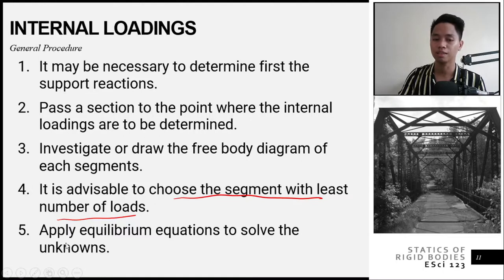Then after that, you apply your equilibrium equations: summation of forces x, summation of forces y, and summation of moments. Okay? Now, for this part, it is advisable to take moments about where you cut. Okay. To understand better, let's proceed with the example.